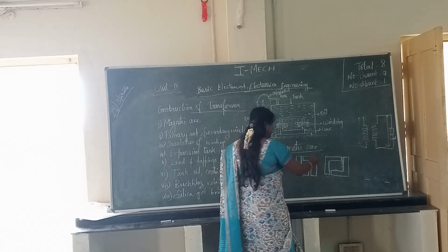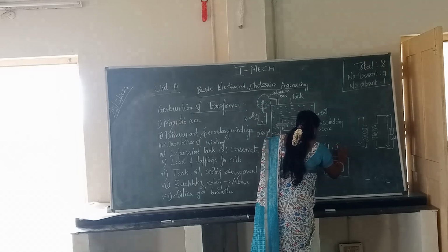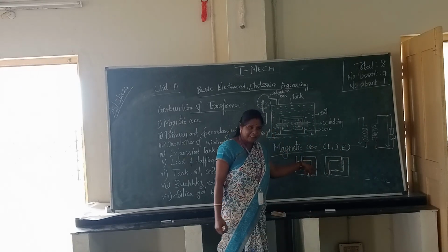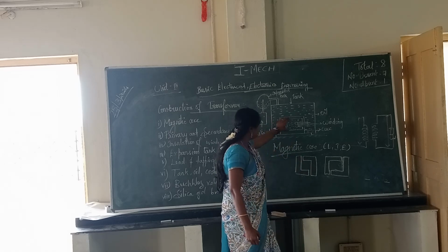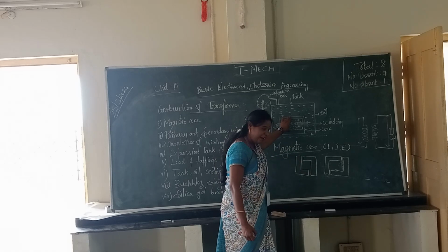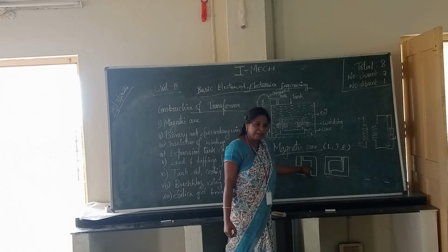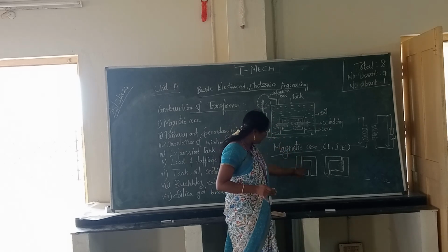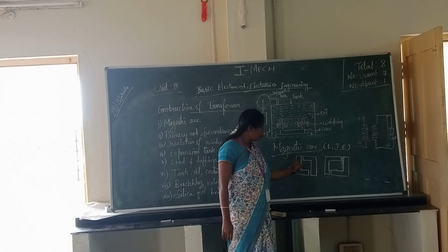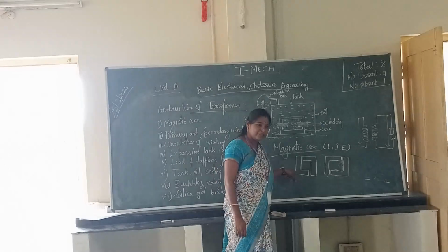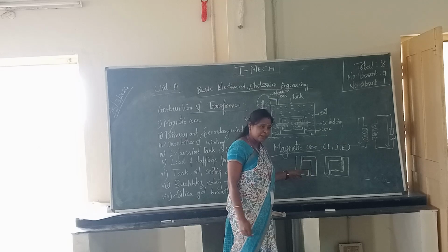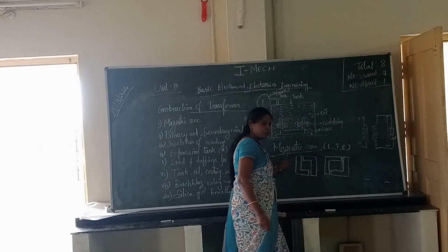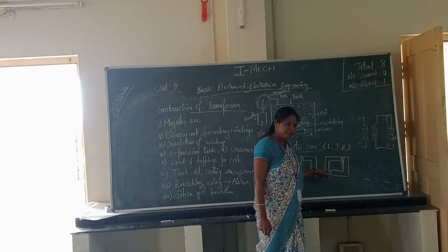There are three types of stamping, L, I and E. Right? So this type is L type stamping, which means the center core part can be made up of two L type stampings. It is made up of these two L type stampings kept like this. The arrangement will be like this, so that it forms a rectangular shape. Yes, it forms a rectangular shape. So then what will happen? A winding can be mounted on this. So this is the center core.